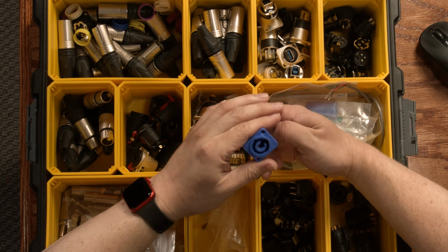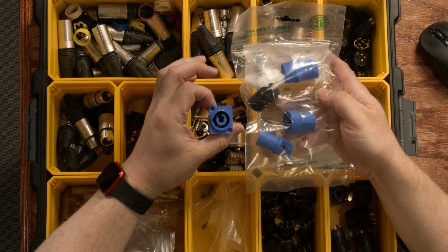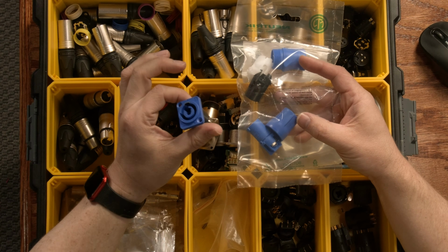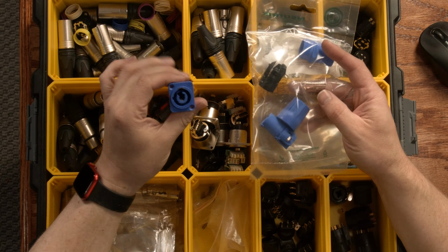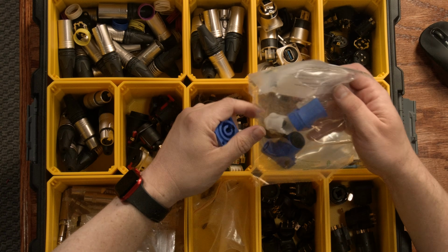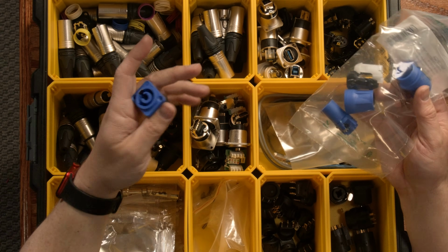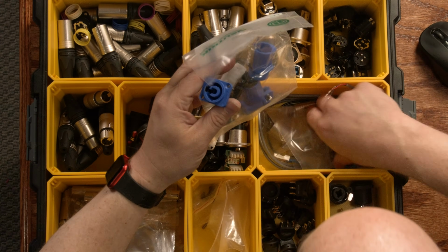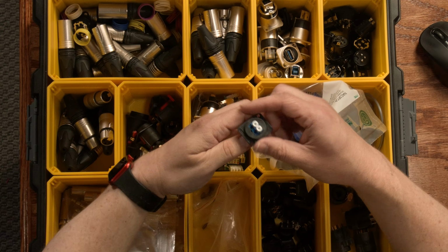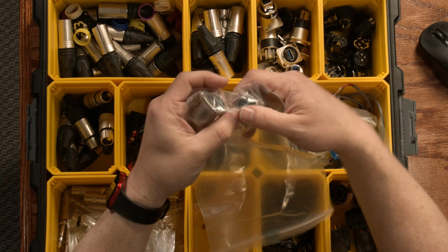This one is what we call a PowerCon, and here's the connector that goes along with that. So that allows you to do AC power, so you can have a power inlet on your device. They also make a corresponding outlet as well. Those ones are colored gray. And they have a newer version, forget the name off the top of my head, that's higher current and meant to be water resistant. These ones are not guaranteed to be water resistant or anything like that, but most of the time that's not a problem for us. So there's those. What else do I have in here? Oh yeah, I've got some fiber, so that's LC single mode fiber connections there, and then higher end similar.